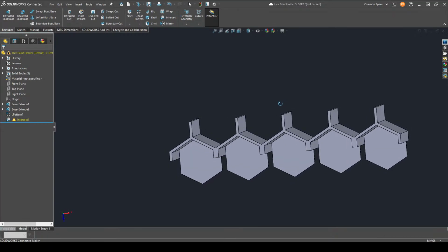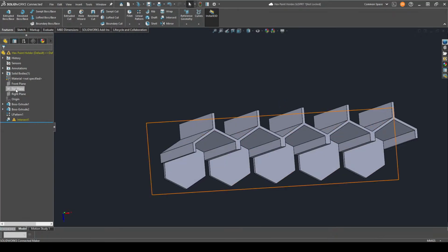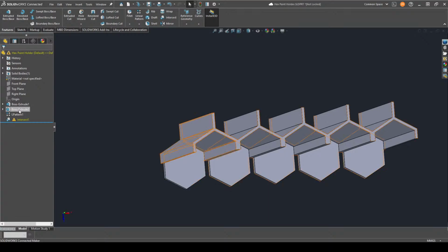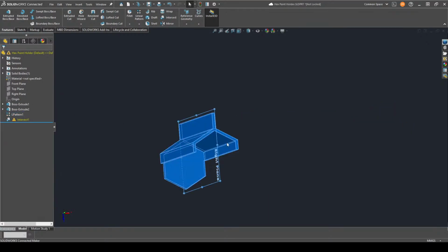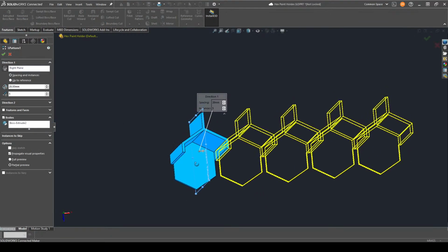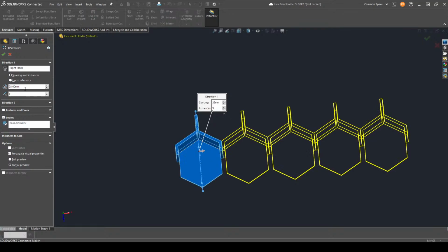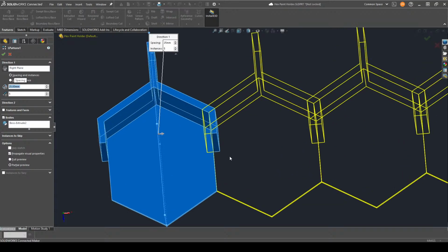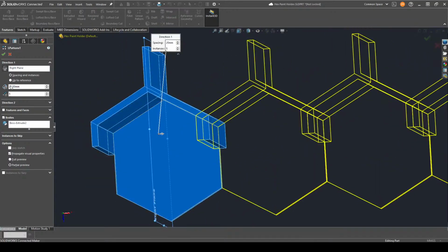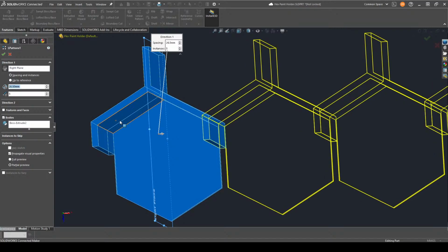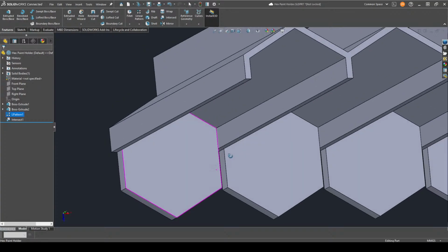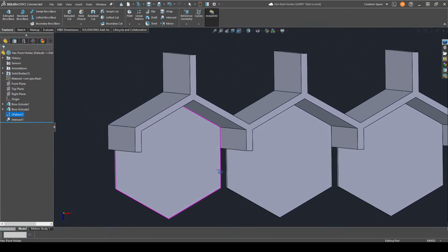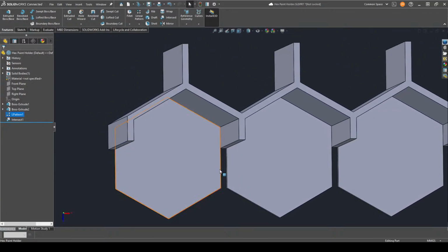And then, oh, what's this? It's not happy with me because these guys don't intersect, because this linear pattern isn't even set up right. Oh, Jamie made some bad choices. So if I put that to 25, you can see, not quite good. So you gotta add that 1.5 there. Now, I could make this all determined by sketch or by equations, which I might do later. For right now, we're just going to do that.